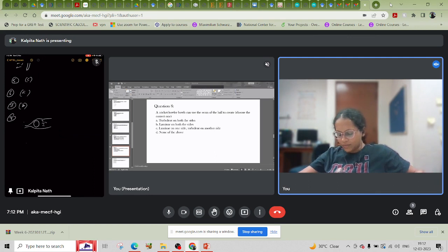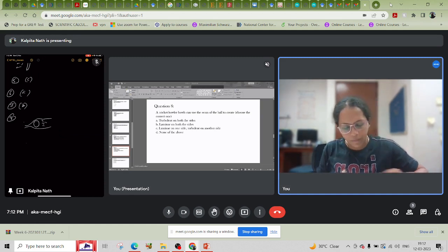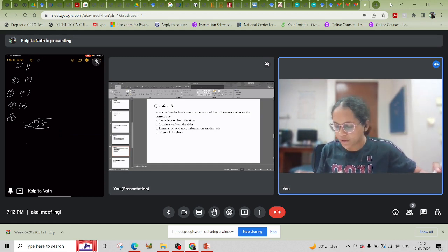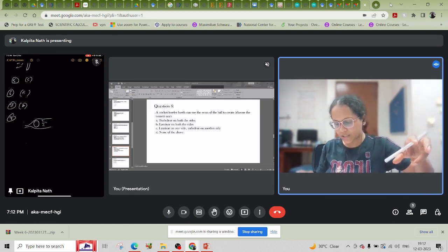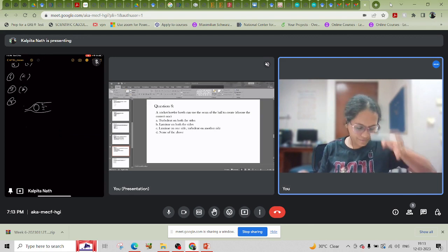However, it turns out the turbulent boundary layer, because of its increased activity and energy, can stay attached to the ball surface to a longer distance compared to a laminar layer. At high speed, if we throw the ball at high speed, the flow will be turbulent on both sides. At moderate speed, it will be laminar on one side and turbulent on the other, due to the presence of the seam in the proper orientation at an angle to the flow direction. I'll show you how. At low speed, the seam will have no effect at all.